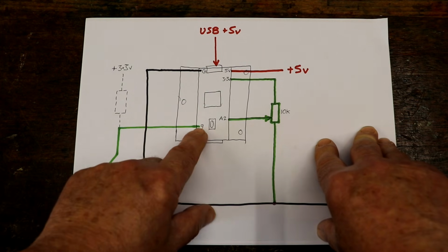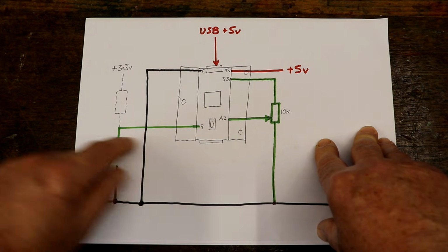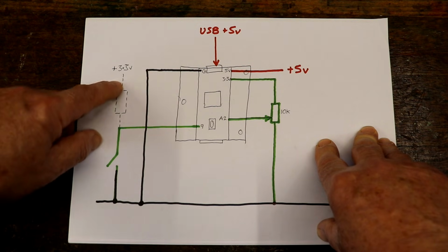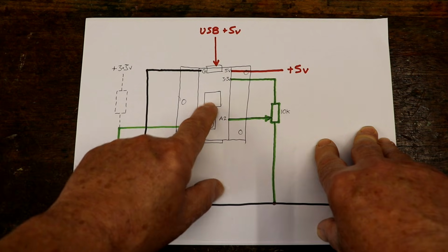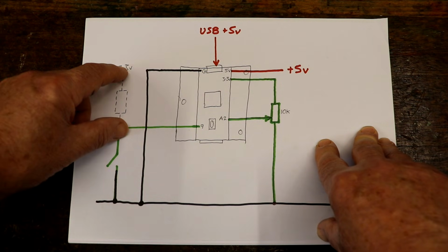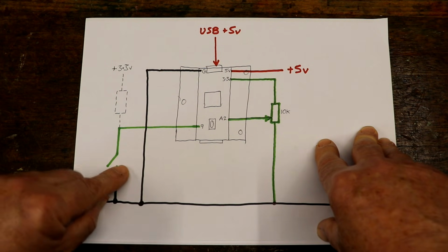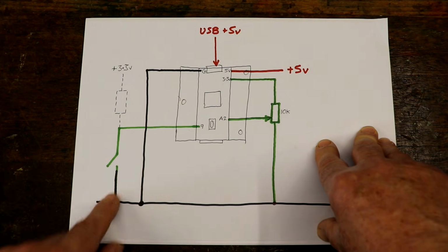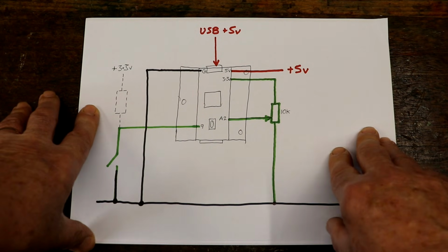And then you set the input to input pull-up in the sketch, we'll cover that later. And that in effect connects a resistor to the 3.3 volt supply inside the Teensy. That means that the input is always high, is always on, until you switch the switch, and then that pulls it down to ground. That way it won't damage the Teensy because it's not switching 5 volts.